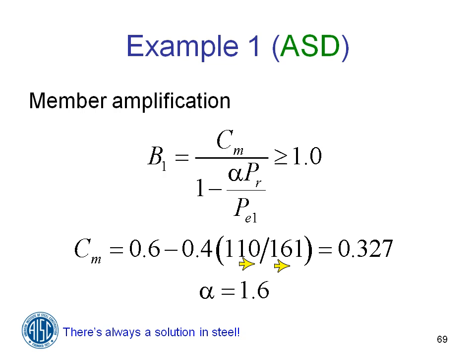Well, that will, but if you've got a design package associated with that, and then you use that reduced modulus of elasticity in the design side, then all of your width-thickness relationships are off, and those kinds of things no longer are valid. So you have to be careful with how you go about applying it. Keep in mind that all we're talking about is a way that we can get away without having to calculate the effective length factor.